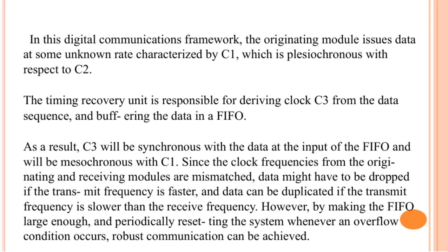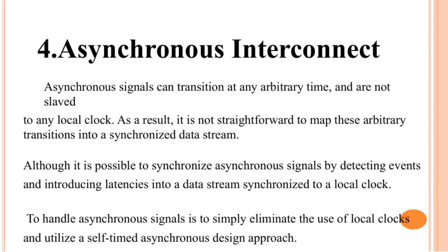The key to managing these differences is to have a sufficiently large FIFO buffer. By doing this and resetting the system whenever an overflow occurs, we ensure that communication remains robust and reliable despite the clock mismatches.